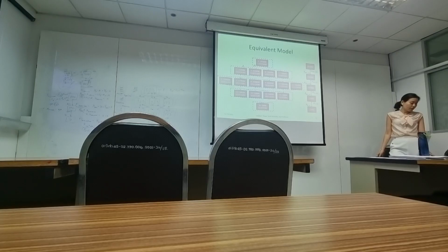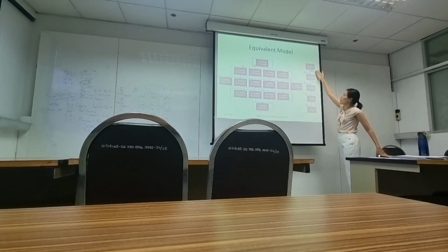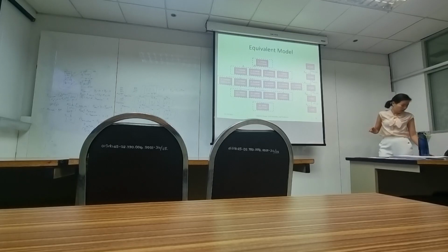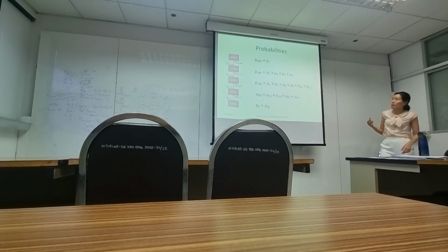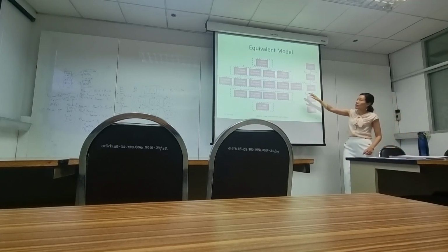So what we first need is to know the probability of being at 200, 150, 100, 50 and 0. And that probability, again, if you have identical units, each unit has only 2 states, being up or down, you can easily calculate the probability of each of these.